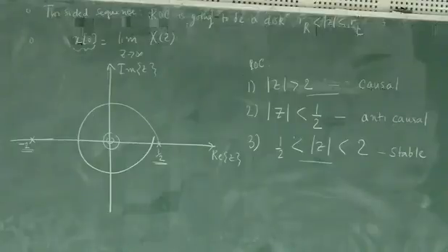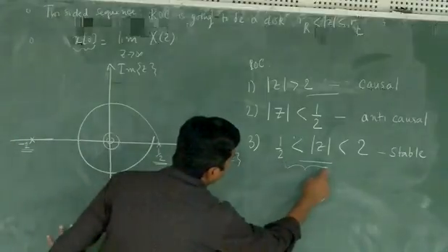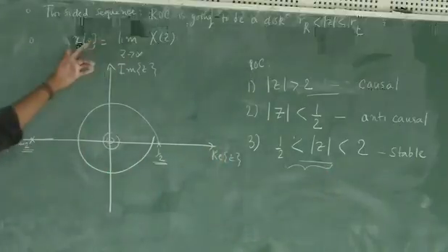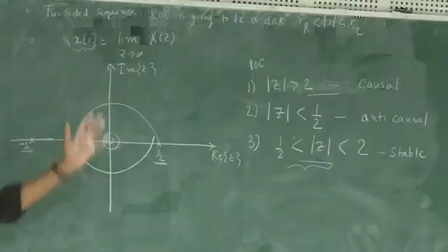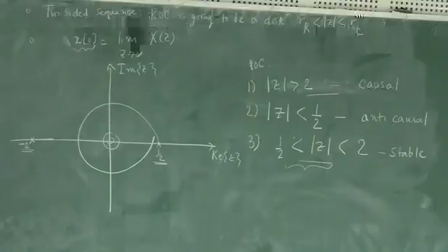Okay? So essentially what this is telling you is that you have this for a two-sided sequence, right? So the moment I say it's two-sided, I have a component of the signal or the system that occurs when n is less than 0. And when I say that, it immediately becomes a non-causal system, right? Or a non-causal signal, correct? And it is still stable though, right?